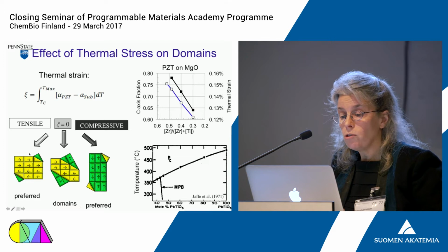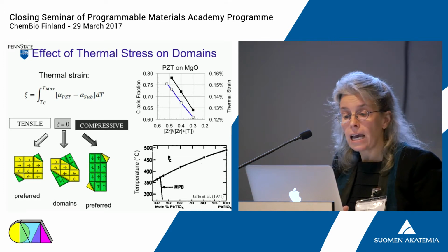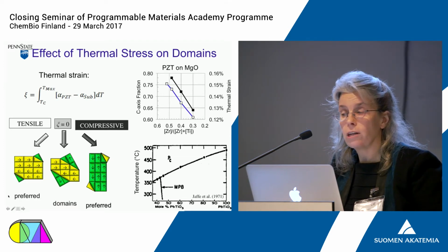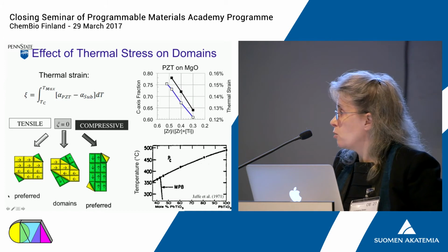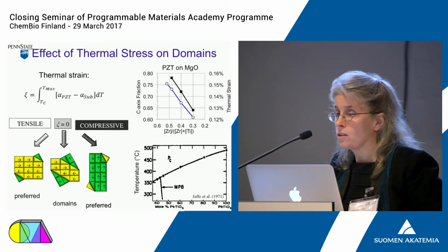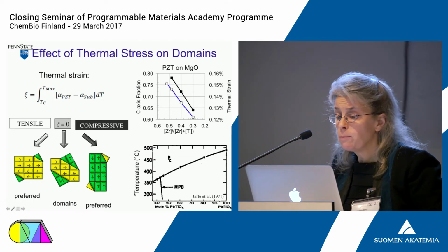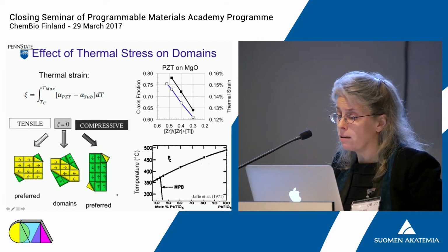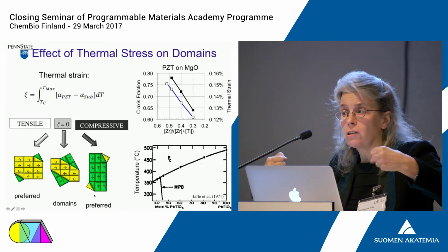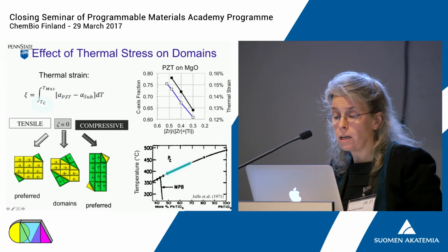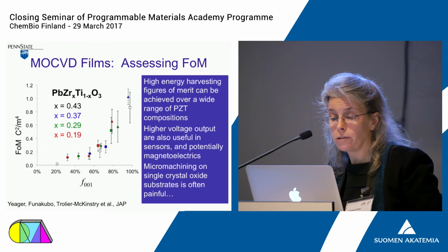This is what you get when you grow those films on silicon, and it's absolutely the worst scenario for an energy harvesting application. So the largest dielectric constant, the smallest piezoelectric coefficients. What we really want is to put the polarization out of the plane of the film by compressing it, by growing it on a substrate with a larger thermal expansion coefficient.